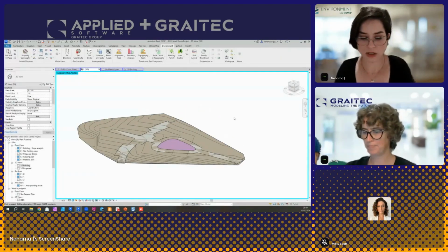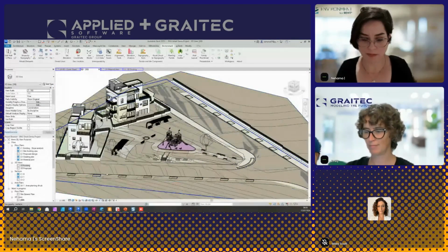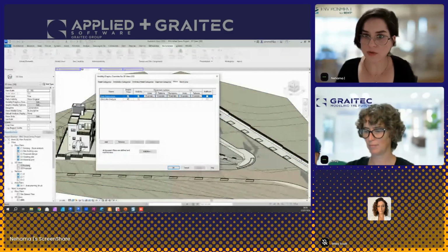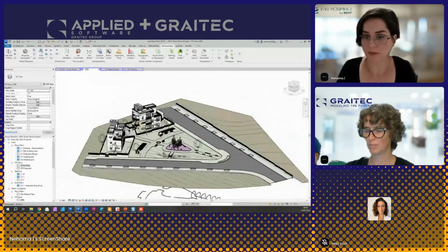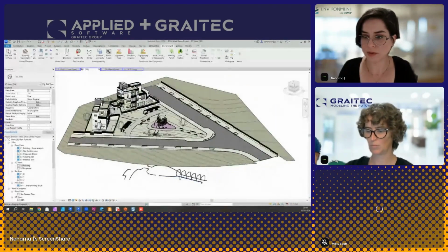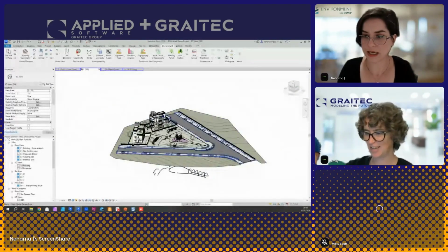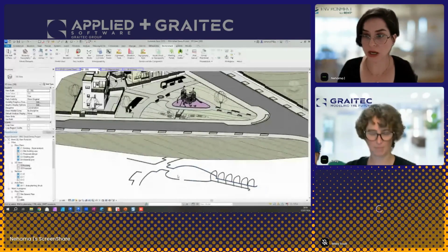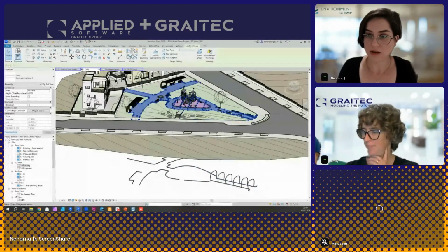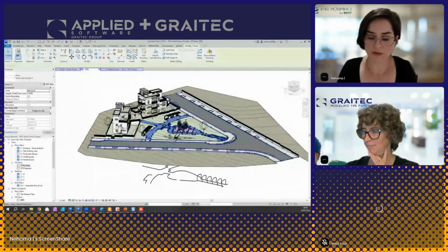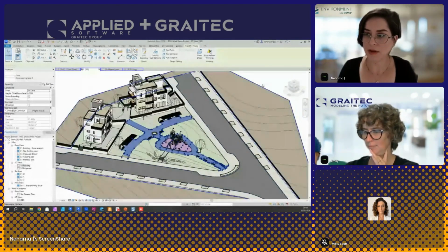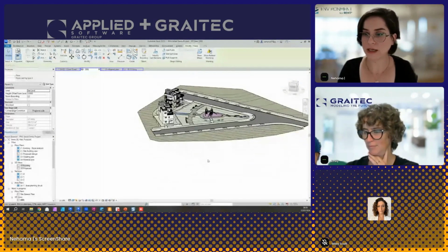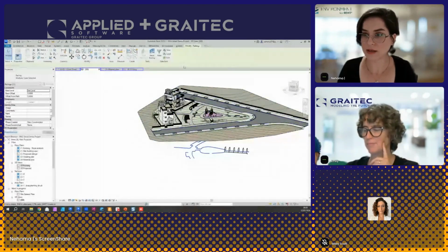And essentially, when you keep all these reference surfaces organized, you can hide them with a work set or with a view filter. You can see some railings stay down. Usually I do host the railings after I modify the floor, because Revit just has a hard time rehosting the railings. But yeah, that's the basic